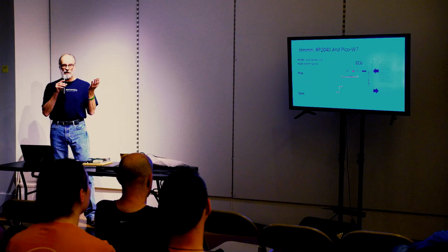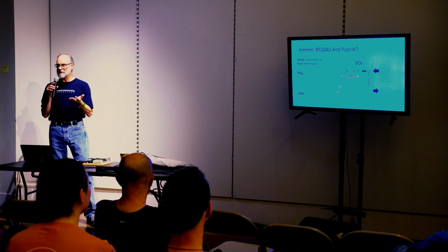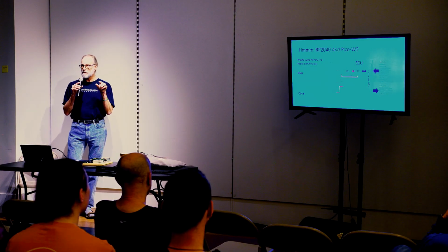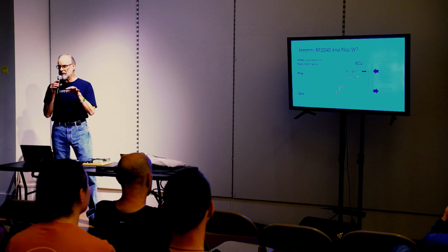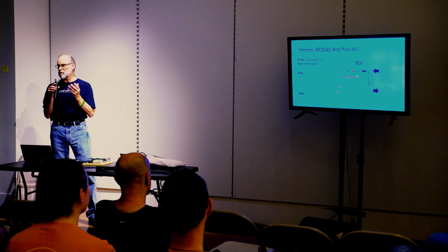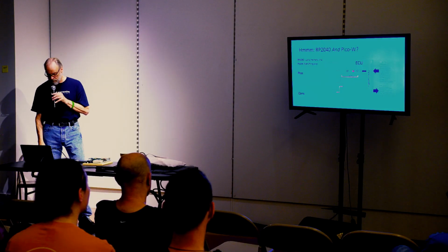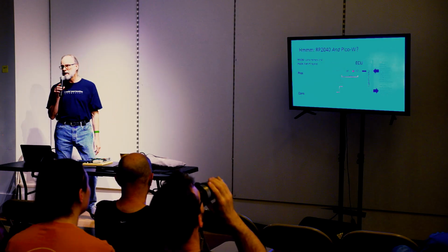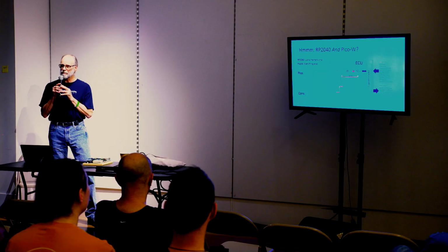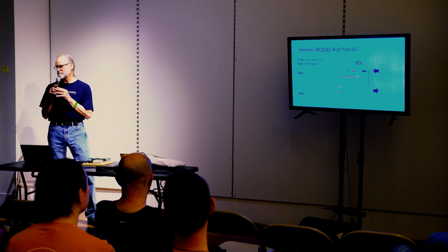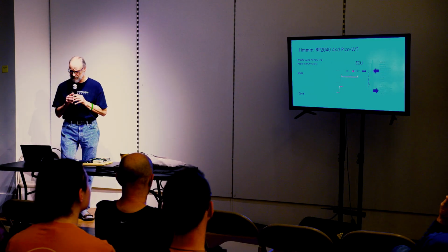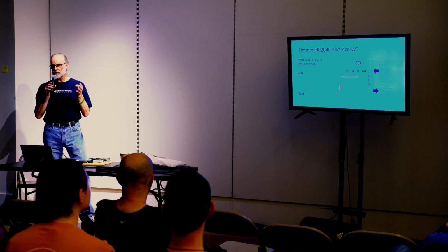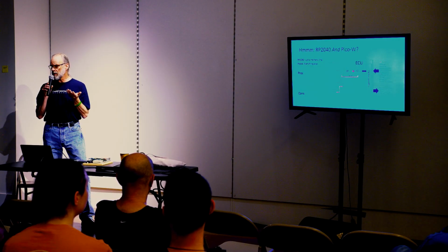So on the plus side, it would have Wi-Fi. I mean, who doesn't want Wi-Fi in their project? And that would be cool. The other cool thing was that it's an identical chip. So even though it's 2 different boards, it's the same mental cost to work with both of them as opposed to just one of them. So that was good. The only con really was that it's not really 5-volt tolerant. Some people claim it is, but Raspberry Pi people will tell you not really. Close, but no cigar. But my takeaway there was pretty much nothing is 5-volt tolerant these days for the new stuff, so I was going to have to do this no matter what I went with, so I just said, okay, fine.